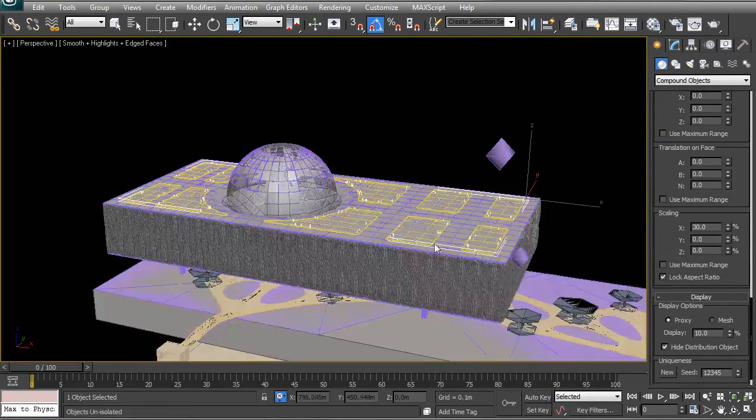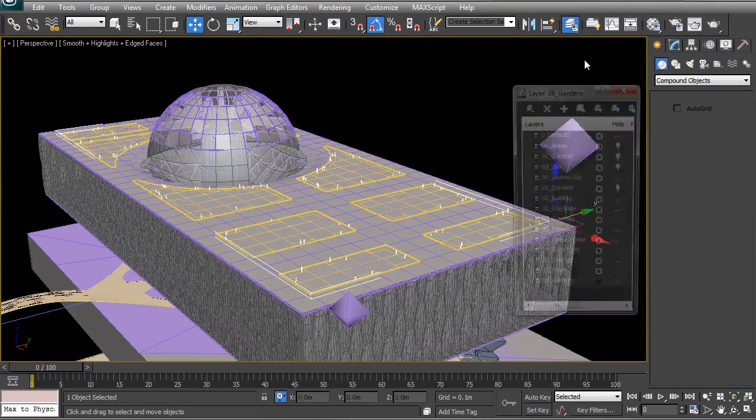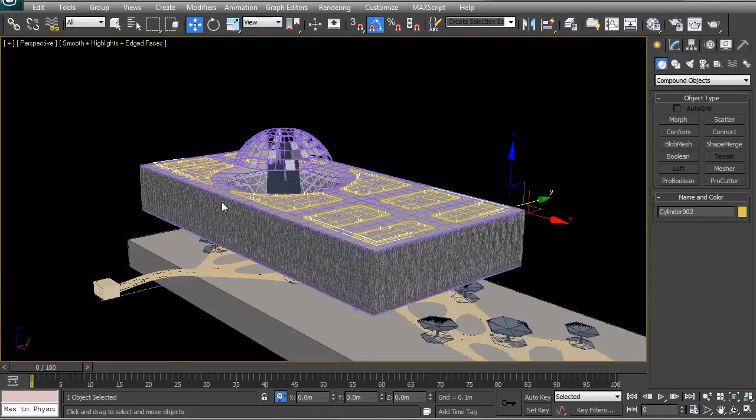So that pretty much brings me to the end of this lesson. All I wanted to show you is how you can use existing objects. So here we used our existing floor slab, and we basically cut out of it, and we made copies and modified those copies so that we can continue to work on our new objects using the referenced old objects. And this is one of the best ways that you can have a speed modeling workflow where you're never really creating anything new, but you're rather just extracting out edges or splines or any type of new object out of your previously created objects that you've already worked on. That's obviously going to save you a lot of time so that you don't have to recreate all of this from scratch. So I hope you enjoyed that.